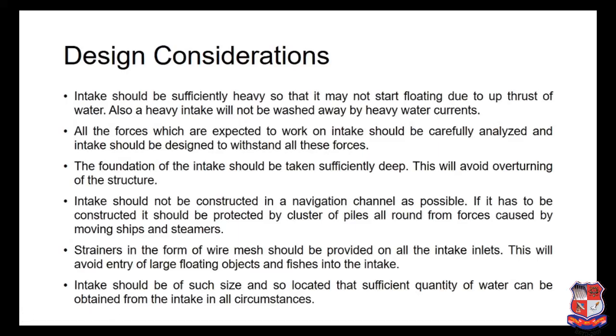And also it should be heavy so that it will not be washed away by heavy water currents during floods. All the forces which are expected to act on the intake should be carefully analyzed, and the intake should be designed to withstand all these forces: its own weight, then uplift pressures, then forces due to heavy currents. All these forces have to be considered while designing the intake.